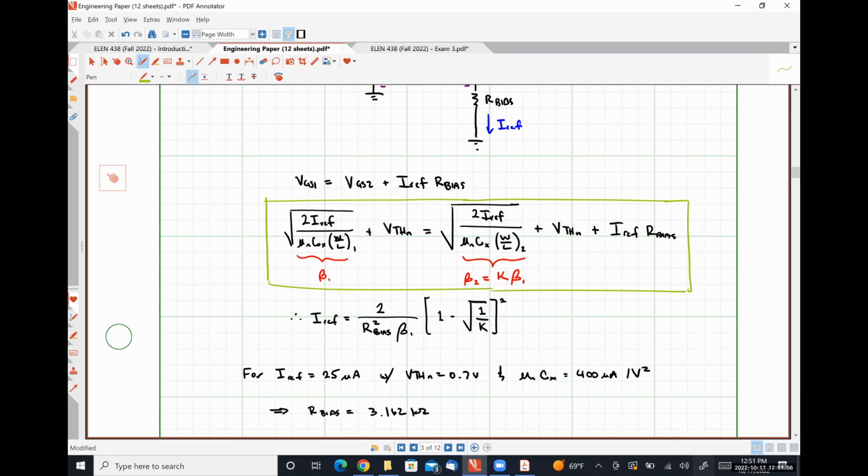You see VDD anywhere? It's independent of supply voltage variation. So this is why the beta multiplier reference is used. It gets results similar to, but not quite as good as, band gap voltage reference circuits, which are highly temperature independent and power supply independent without having to use mixed technology. So no BJTs and MOSFETs, only MOSFETs to deal with here.